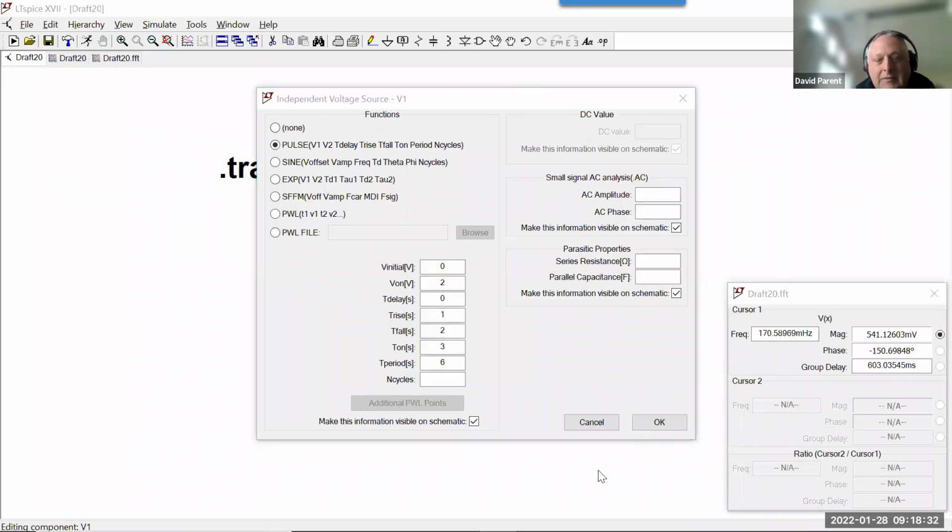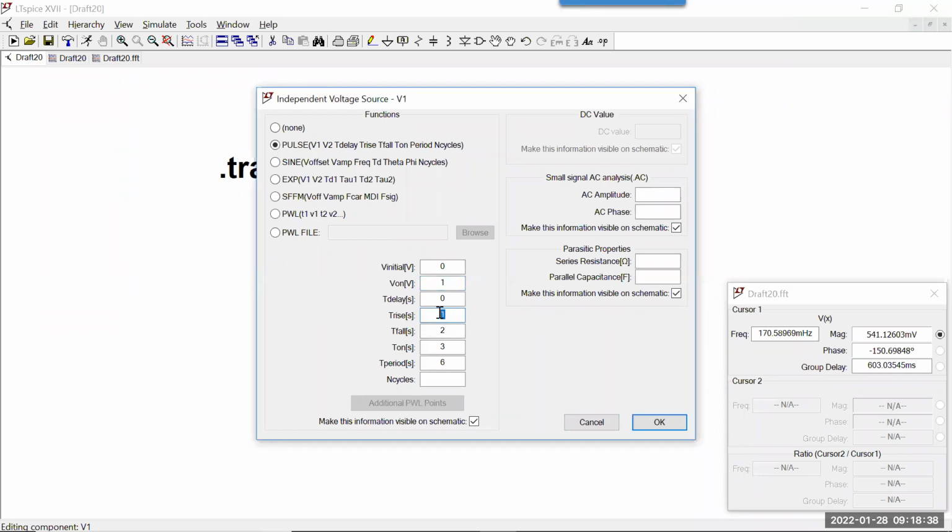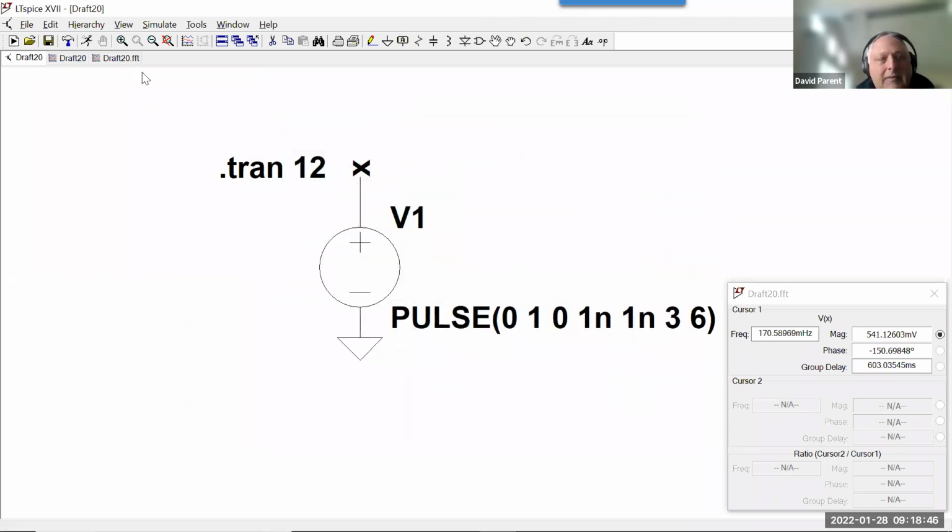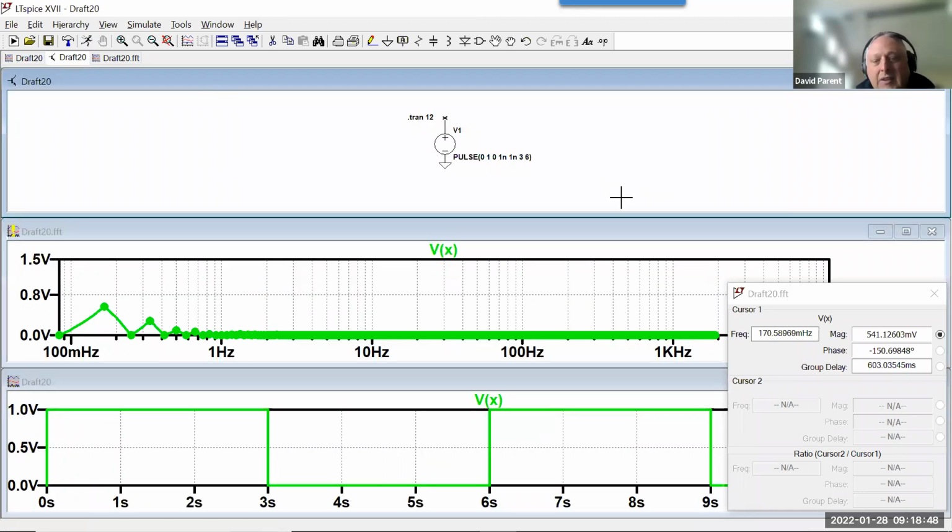It's a great question. So what I'm going to do is go on for 1. I'm going to go up very fast. I'm going to go down very fast. And I'm going to stay on for 3. So this should be a 50% duty cycle. Okay.